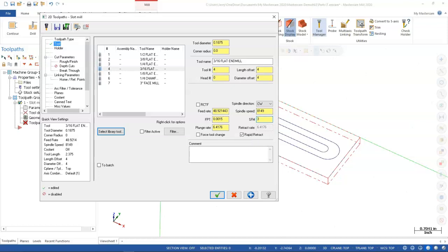We'll back that off to 300 surface feet. I think it would probably be a 3/16, and if I got a coating for it, I think I could manage the 61. Because aluminum, I would be looking at 800 surface feet, somewhere in there. All right, the feed rate at 36. Yeah, even though I think maybe it could handle that.